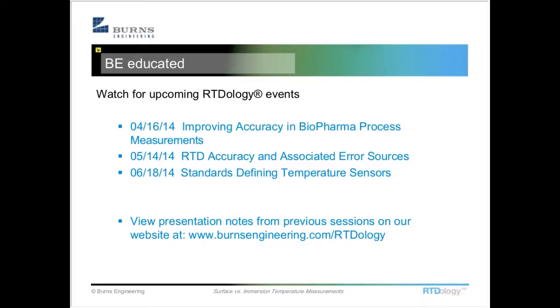The other aspect to look at there might be radio frequency and electromagnetic interference. Thermocouples are a lot more susceptible to that, so I always recommend putting a transmitter as close as you can to that thermocouple. And if you do need to get a distance away, use shielded cable and don't run it near anything else that's going to potentially cause some interference.